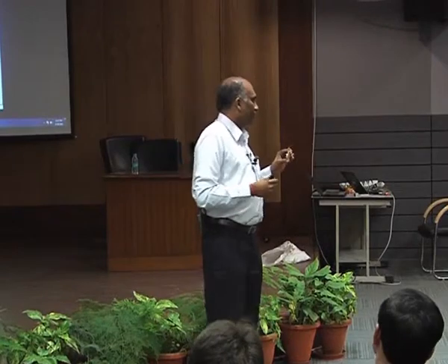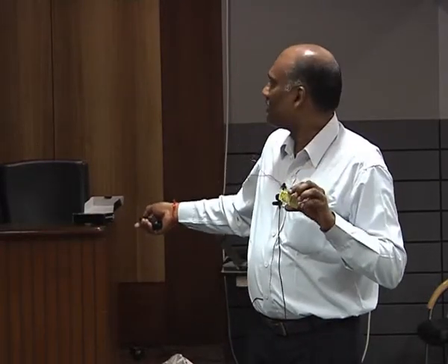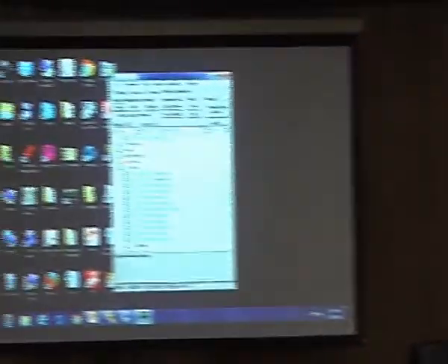Those pins are to be configured here. When I come to IO settings, that is what I mean by input output. The temperature, potentiometer, as well as the digital LED, are nothing but IO values, input and output, for our application here. Those corresponding IO values need to be set up here, so those IO settings have to be done. Which particular pin has to be used? As I said, pin number 20 is connected to the temperature sensor. What is pin number 20? It is equivalent to AD0 or DIO0, D0. That is this particular one, which shows here as the first value. Now, where do you get this information? You can get it from the XBee data sheet.